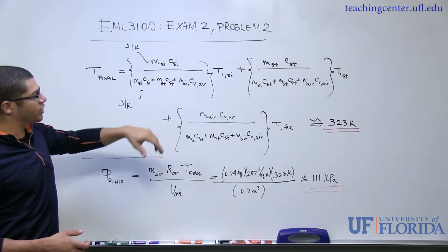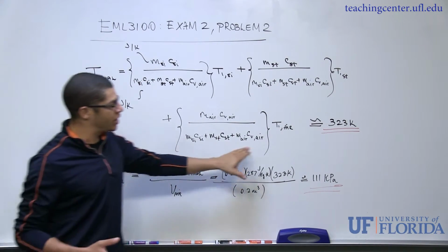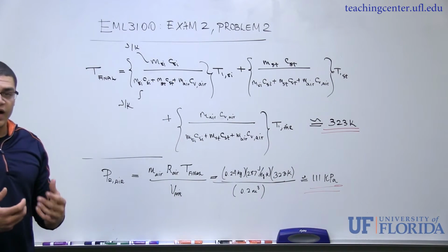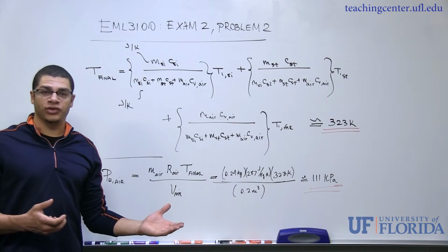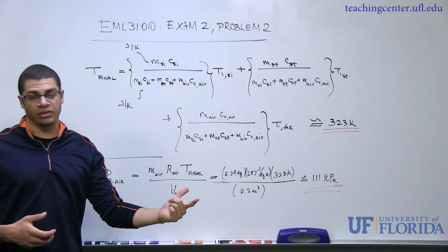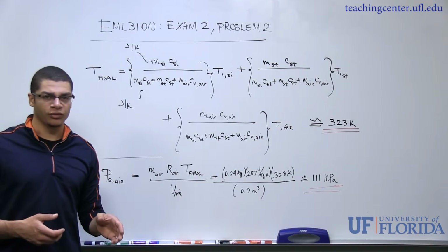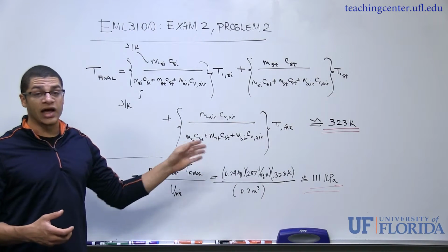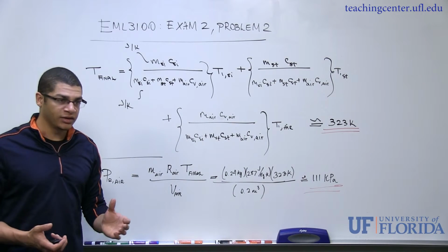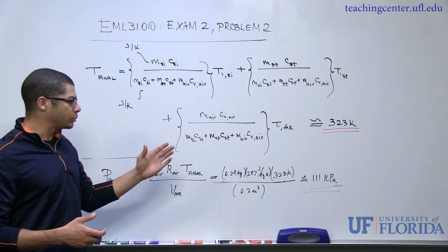So each of these terms and their temperatures are present here, and after plugging everything in, we get a temperature of approximately 323 Kelvin, which lies between the minimum temperature, which was ambient, or 293 Kelvin, for both the steel structure and the air temperature, and the maximum temperature of the problem, which was about 523 Kelvin. And again, because it lies between the minimum and maximum temperatures, the second law has not been violated, and thus this provides us with a sanity check for the algebra and the problem.